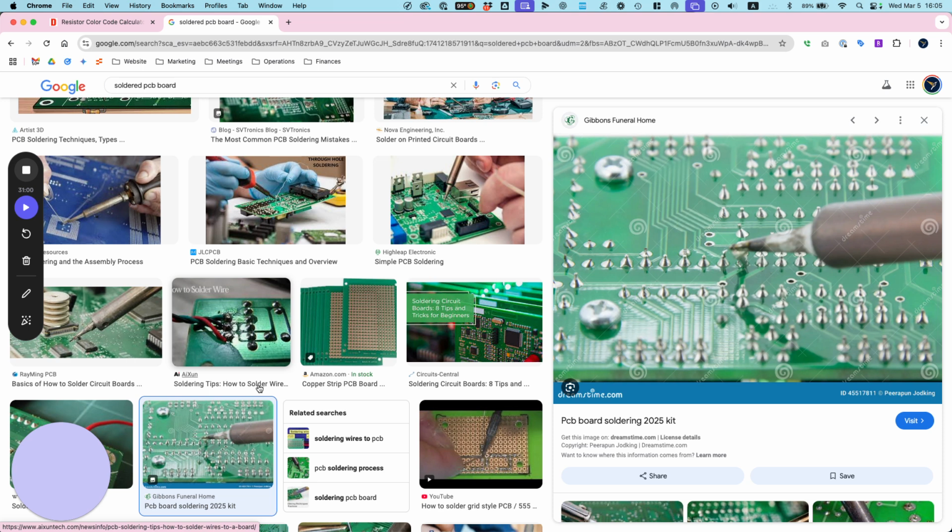Now there is a risk to doing this, that if you ever put this against a metal surface, it's going to short it out. Actually in fact, even if you didn't do a bridging like this, if you put this bare circuit board against any metal surface, you're going to short things out. So you should have some form of buffer in between. That could be as simple as a little plastic sheet or something like that.